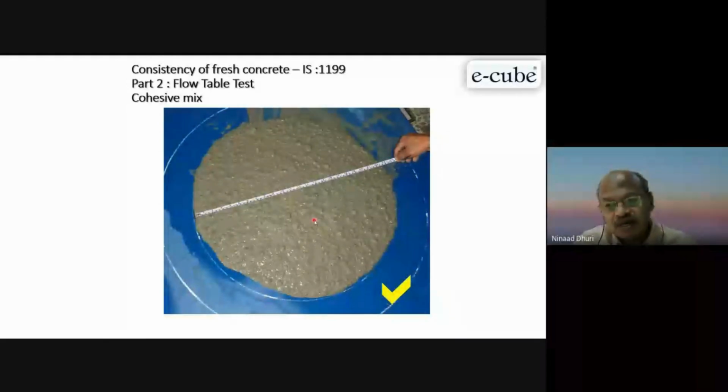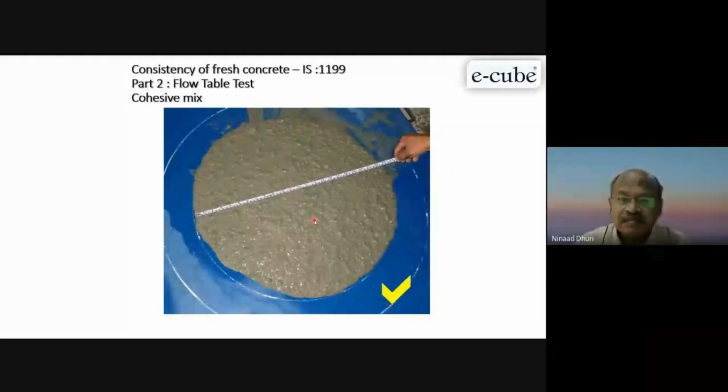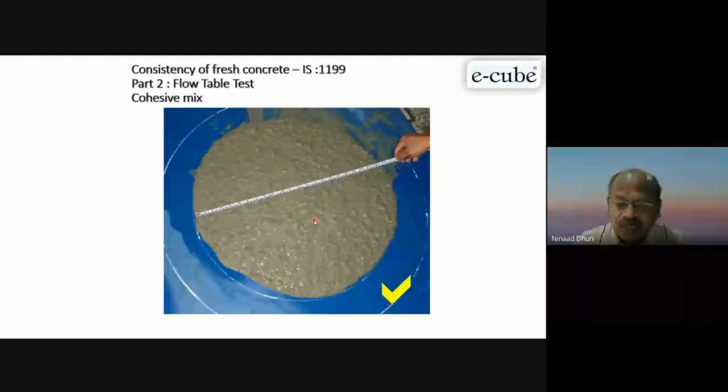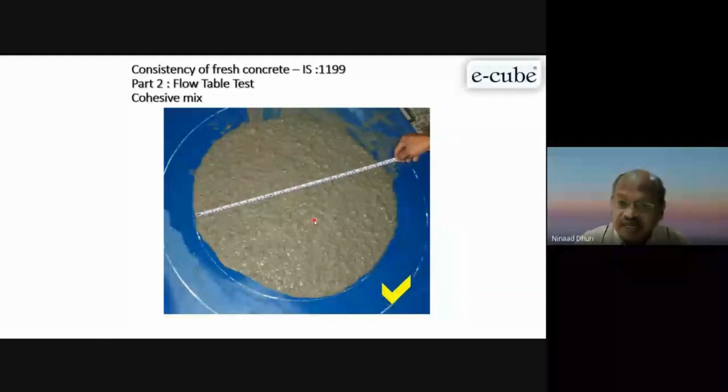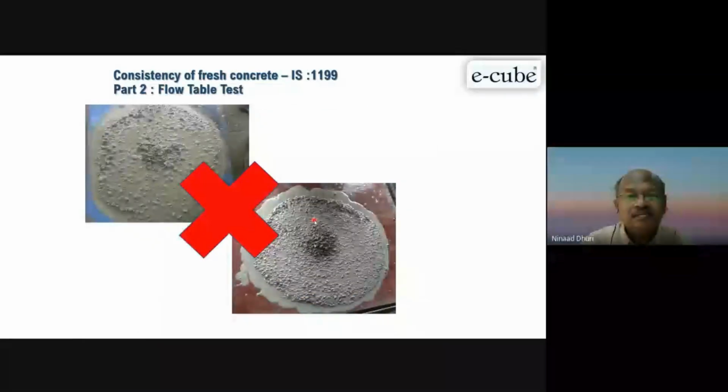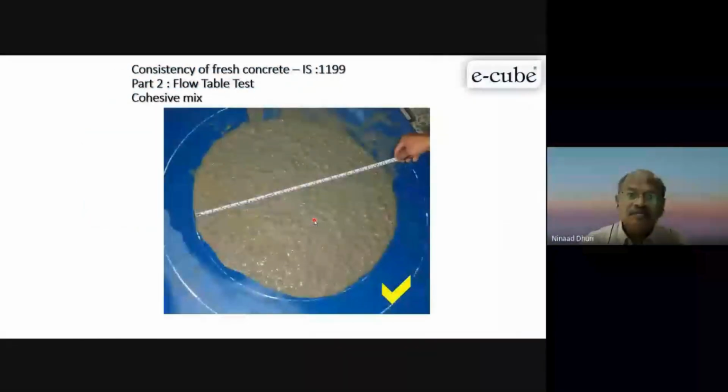And once you pump the concrete, it has to be vibrated and then finished, so you need at least half an hour to 45 minutes for that. You have to consider all this time, and accordingly ask the RMC vendors to supply concrete at a particular flow and a cohesive mix, not a mix like this. It is not acceptable. There are a lot of issues in the structure.